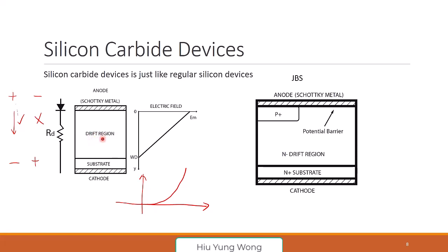But why do we want to do that? You must say, hey, why make this so thick? Any idea why I want to make this thick? Anyone? Remember, when we're talking about power devices, two things are the most important. Reduce the capacitance. Say again? You make it thicker to reduce the capacitance? You want to reduce the capacitance? You said what happens when you reduce the thickness, right? My point is, why do I want to have a thick drift region?